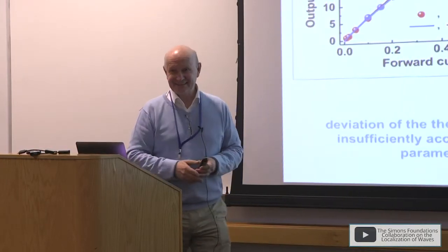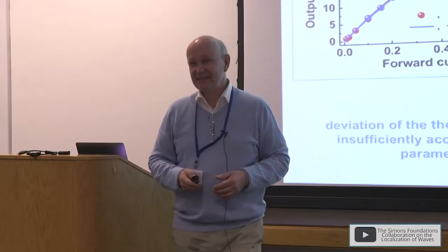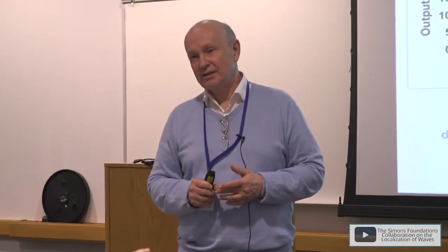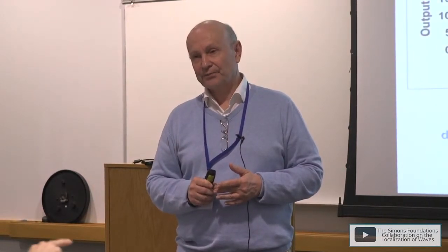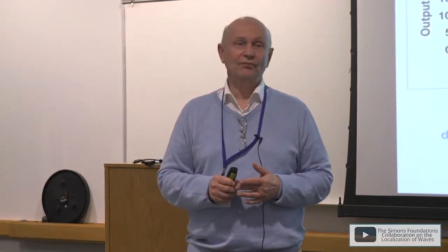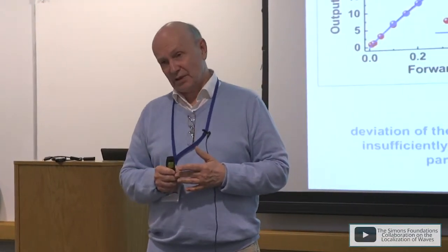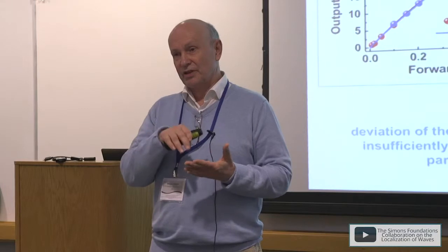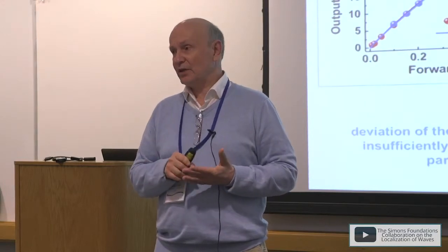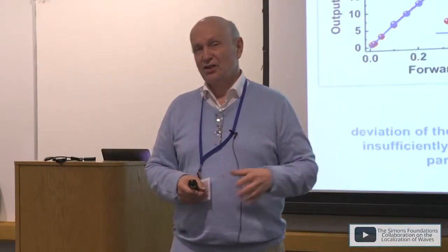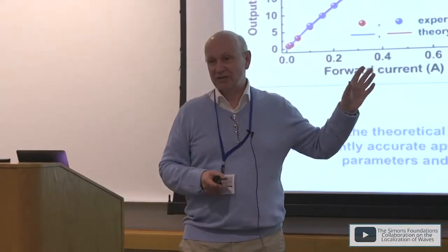I have a question. Are there any thermoelectric effects here? You have different temperatures, right? Yes, a gradient. So are there fields generated by that? Are they important in this case? They are not important. We estimated the thermoelectric contribution to the currents, and they were approximately a few percent of the total current. So actually, this is just typical drift diffusion contributions.